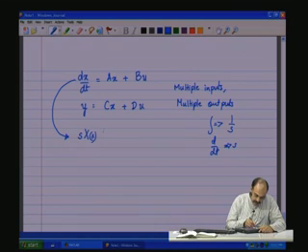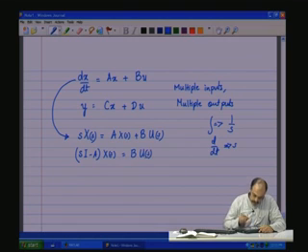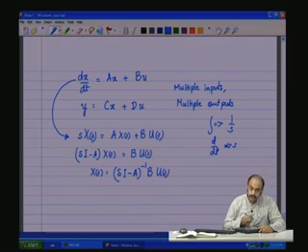So, you can say s X(s) is equal to A X(s) plus B U(s), or (sI minus A) X(s) is equal to B U(s), or X(s) will be (sI minus A) inverse B U(s).